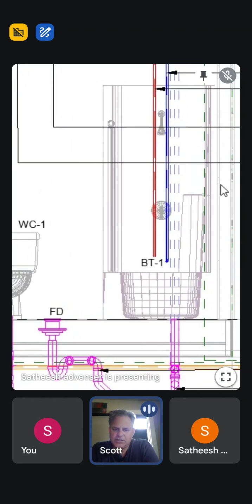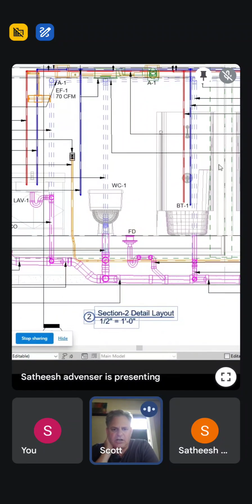It's almost like you have this sheet, and then you have a dumbed down version of this sheet that shows where your penetrations come through the floor. You have the elevations of all your outlets, and the call outs to the fixtures we're using, the call outs to the toilets. You should see a WC1, where WC1 is water closet. It's a Kohler K whatever, the brand name. All that should be tied to a list somewhere that we can easily grab that data and order parts from.